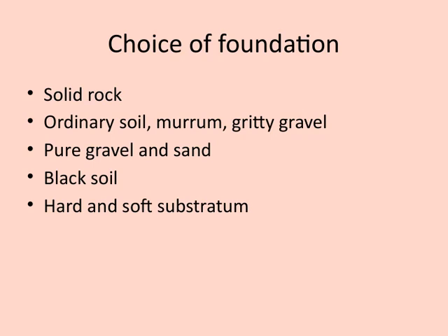When it comes to the choice of foundation, the type of ground you're working with is absolutely crucial. First, we have solid rock, which is ideal because it provides a very stable and strong base for almost any structure. Next, we encounter ordinary soil, muram, and gritty gravel. These materials can be suitable, but they often require proper compaction and sometimes stabilization to ensure they support the load effectively.